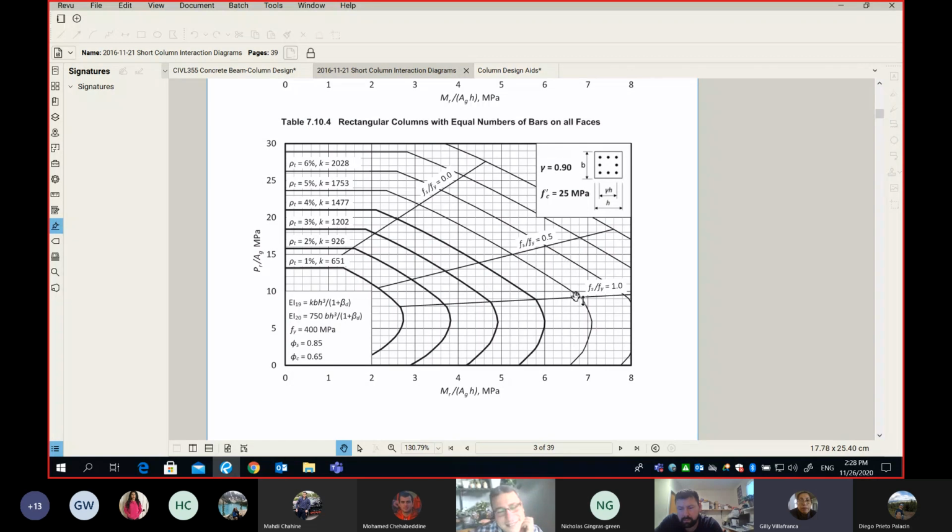Never? Because it's h prime over h, that is the ratio. So if it's 1, then there is no h prime. It means your rebar is outside your concrete box, because h is equal to h prime, correct? And if h is equal to h prime, it means you placed half of the bar outside your concrete. As simple as that. Anyway, that's for fun only.